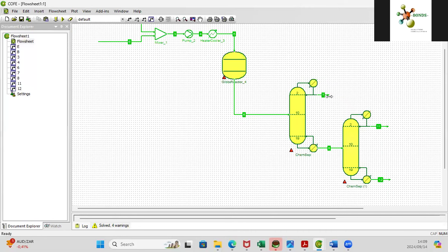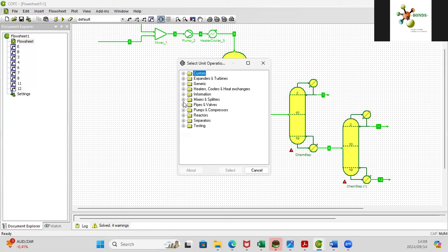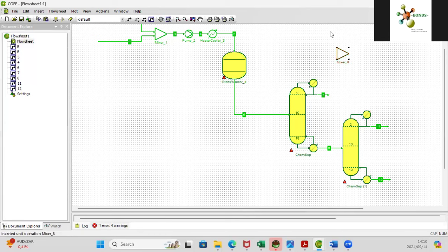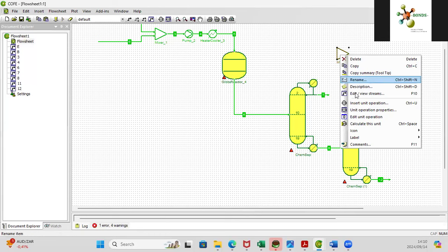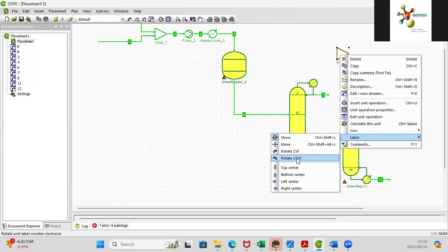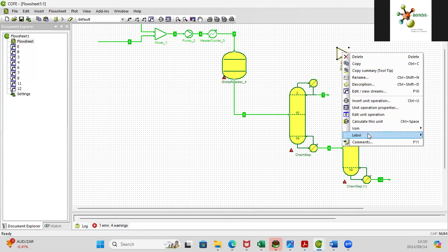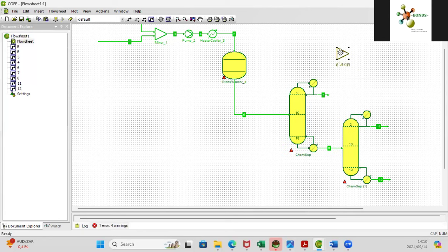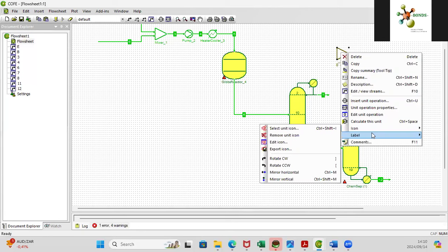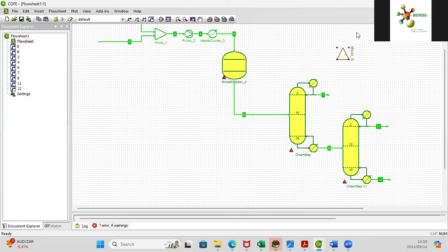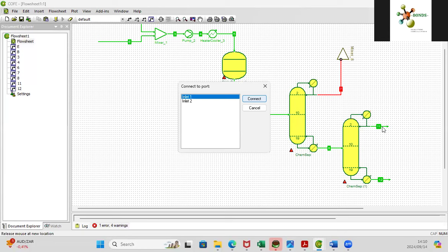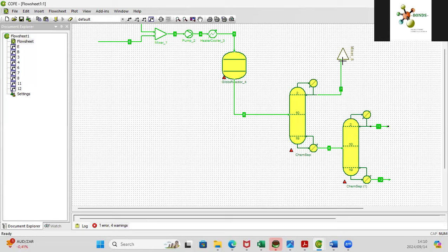Then what we want to do is recycle back our benzene. So the first thing I'm going to do is combine the two outlets. Please note you are allowed to rotate this. So if this does cut, I will continue from here. I'm hoping we'll be able to finish this episode. So let's rotate the unit. Looks like I'm not rotating the unit, I'm rotating the labels. Rotate the unit. So we're going to combine those. That one. That two.